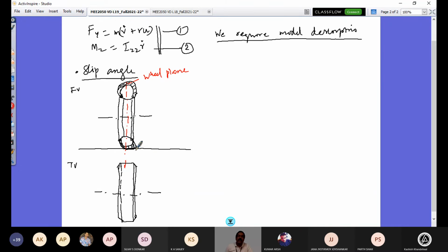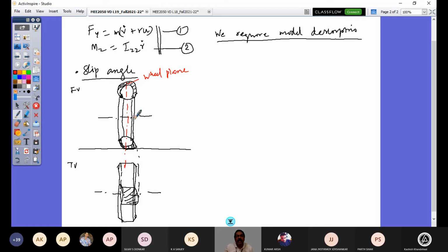And you see this contact patch now, how that would be appearing in the top view. It would be something like this, skewed, right? So your contact patch would be something coming like that. So this is my contact patch. So if I project this, it will come here. So this contact patch is not in this and it has come here. And on the top, it is symmetrical as this is rolling and the tire comes in contact in the contact patch, it won't get skewed like that. It is skewed like this all because of a side force.